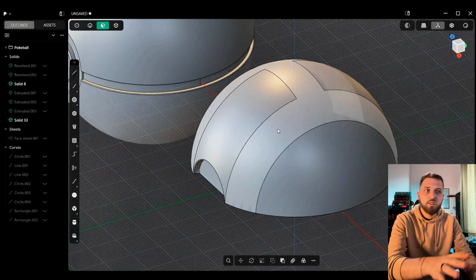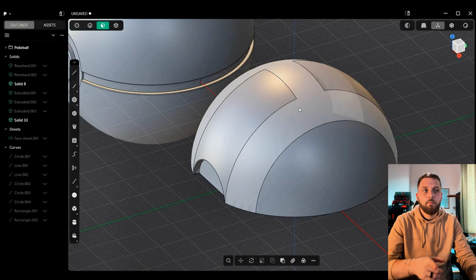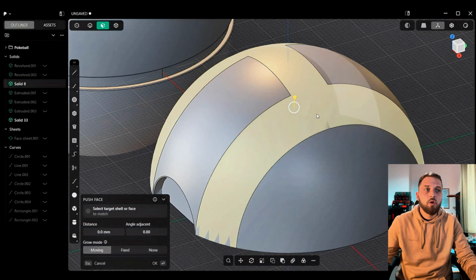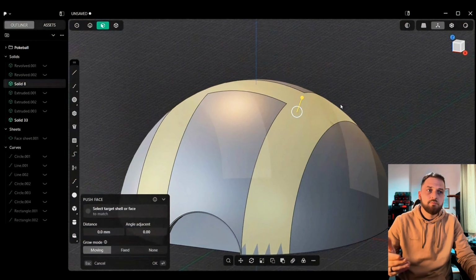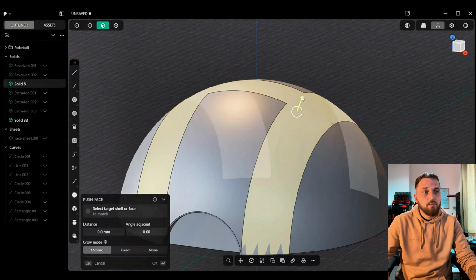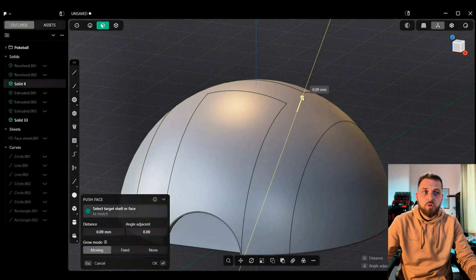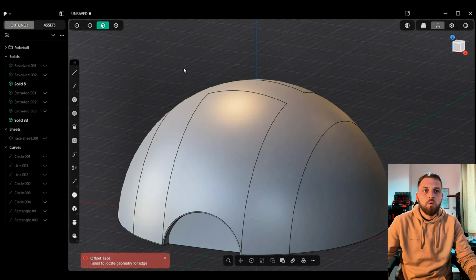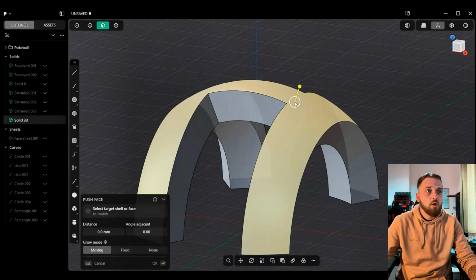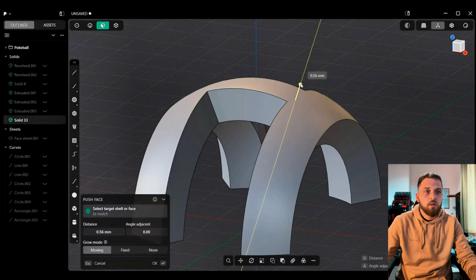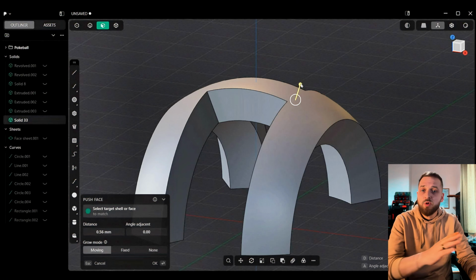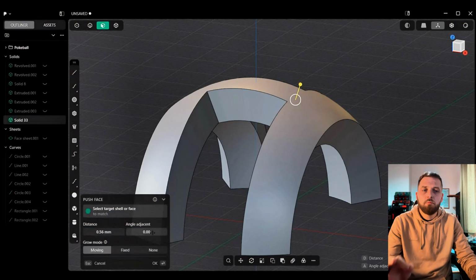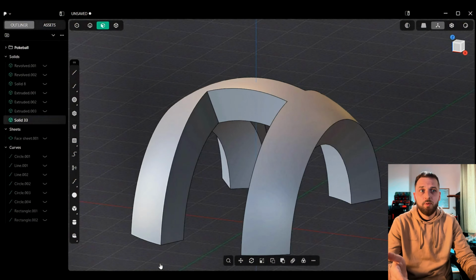and be separate body. Now, what you want to do though is, so there's no issues when you've taken it apart, drag the face on the outside out just a little bit. Oh, it filled that part. But right, let's do it to this part. There we go. Brought it out by 0.56. Doesn't matter how much you bring it out, just remember the number that you bring it out by, because that'll be important to line things back up.